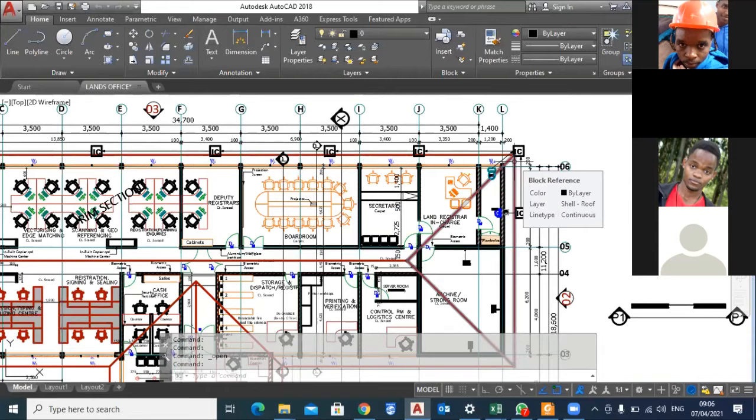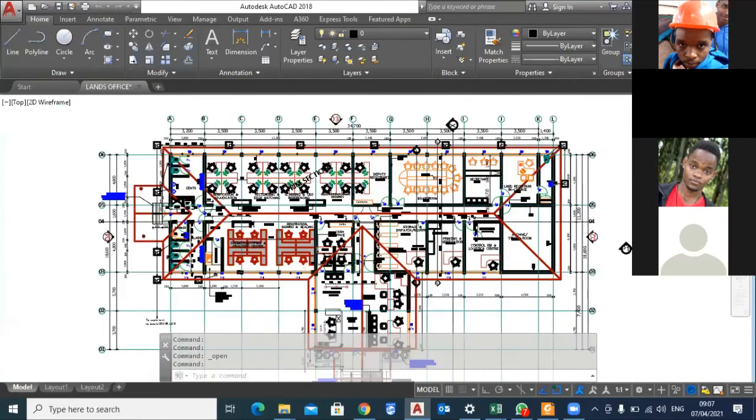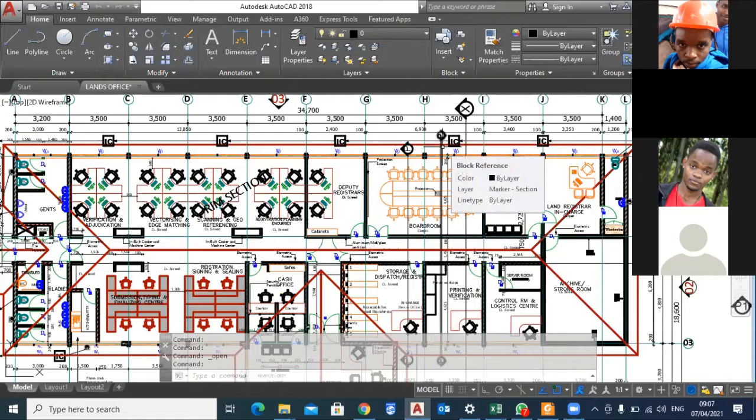We look at the beam angle and the distance of beam travel, how far that illumination can travel. They can illuminate comfortably up to 10 meters. For that one, we just use a rule of thumb, 10 meters, or for street lights, you can use 25 meters, street light of 50 watts.